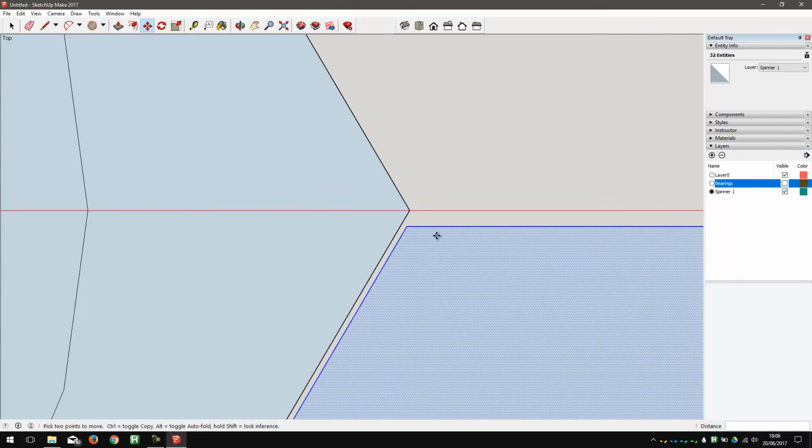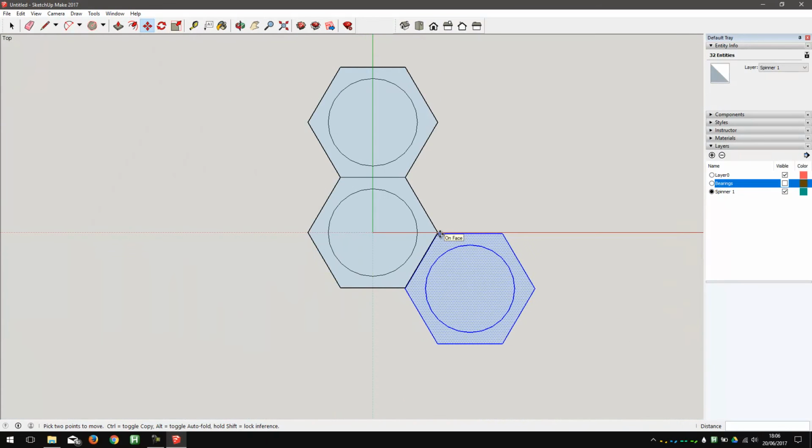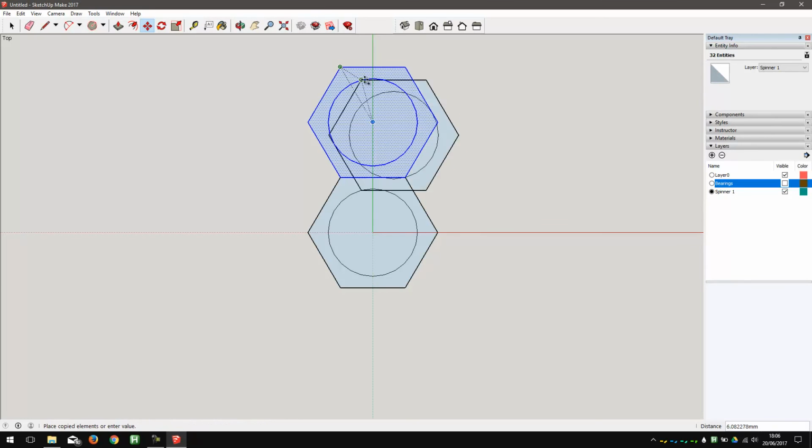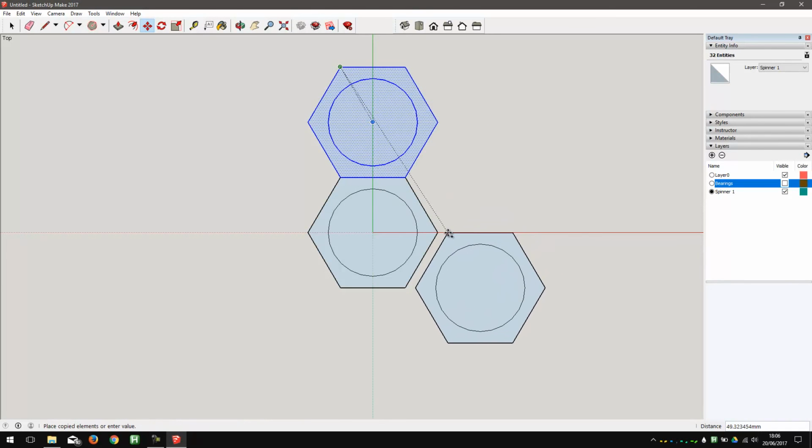Okay? So if you want SketchUp to do the hard work and make everything lined up perfectly, then what you want to do, and I'll highlight that again, get my move tool, tap Control to get the plus. You want to snap two things. So if you go on there, it tells you by highlighting the little endpoint, green, and a little bubble pops up that says endpoint, you know you've got that endpoint. Now I click once with the mouse, let go of the mouse button, move over to here, and make sure I'm touching that point there. And I know I am because it clicks green and it says endpoint.